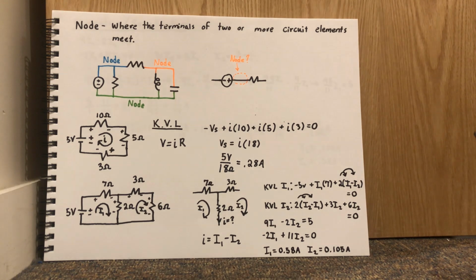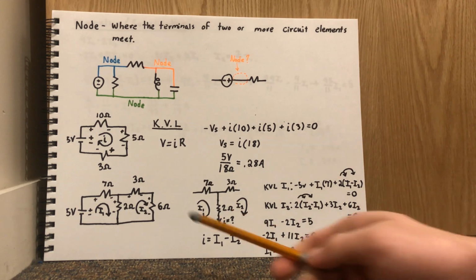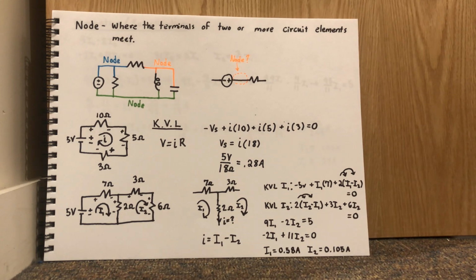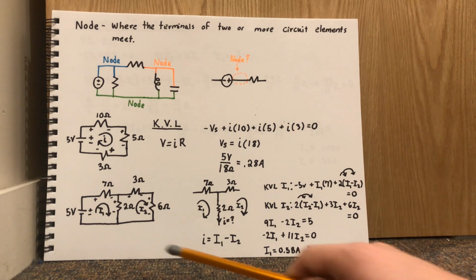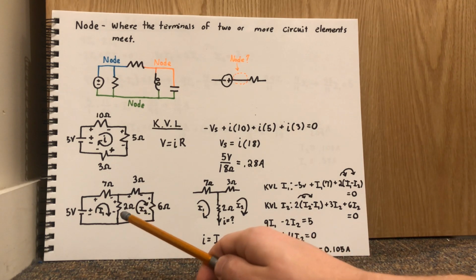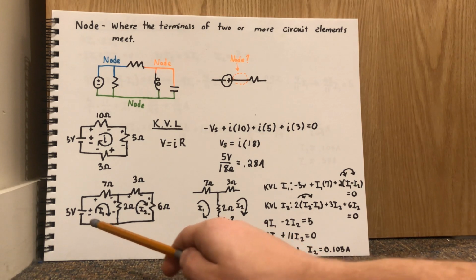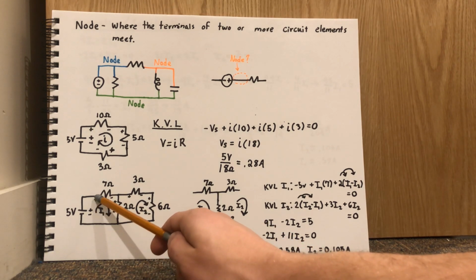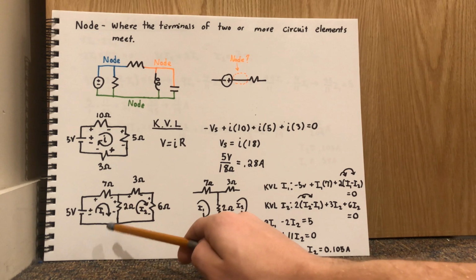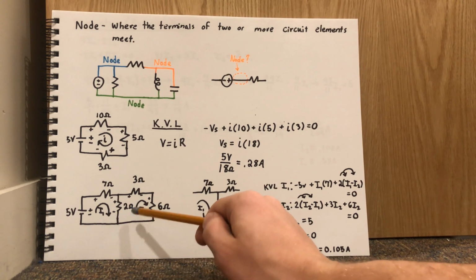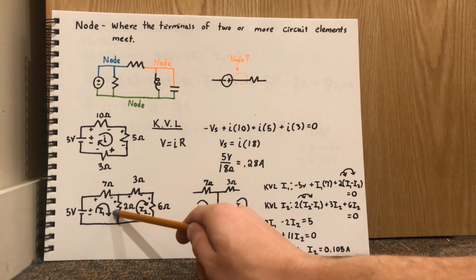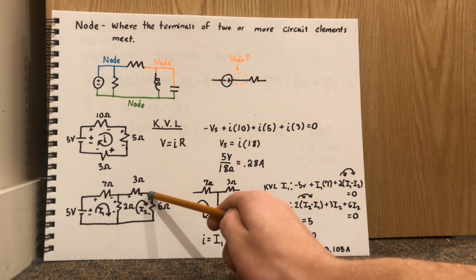So now what's going to happen if we have a more complex circuit like this one drawn here? We're going to want to break it up into 2 different loops, an I1 and an I2. And we're going to do the same thing as earlier. So with our sign convention, again, we're going to see that this is a negative, positive, positive. And then whenever we're using this one, we're going to see that this is negative, positive, positive.